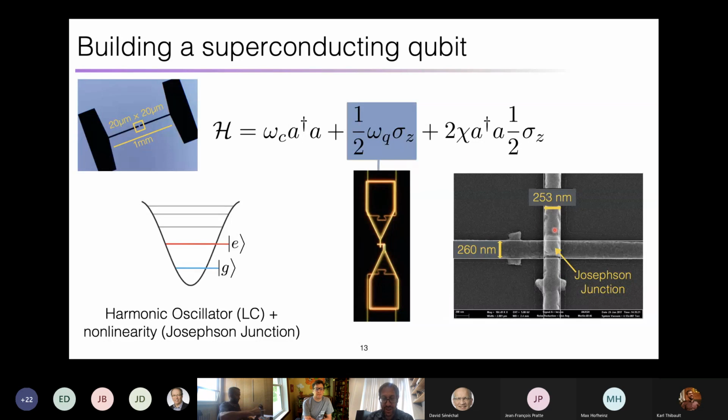And then the other piece is the qubit. This is what's called a superconducting transmon qubit. That's a fancy name, but it's actually a very simple circuit. Physically, it's like a Josephson junction with an antenna. This is the Josephson junction. It's just two pieces of aluminum, where you see one wire and then another wire on top, and in between the different steps of evaporation, we grow a very thin oxide layer as a tunnel barrier.